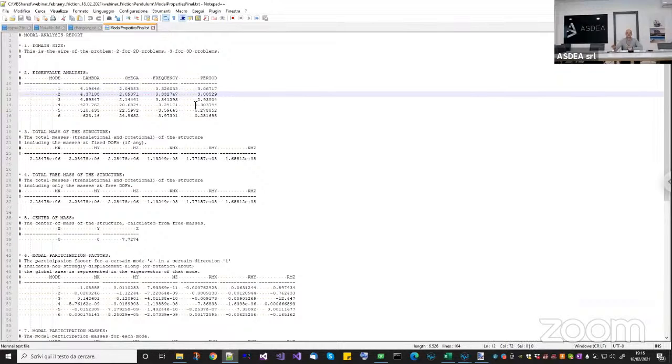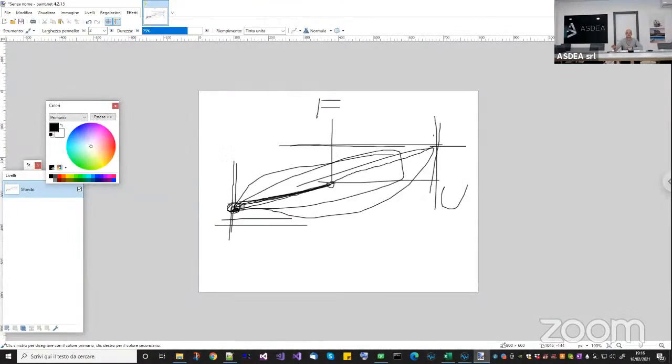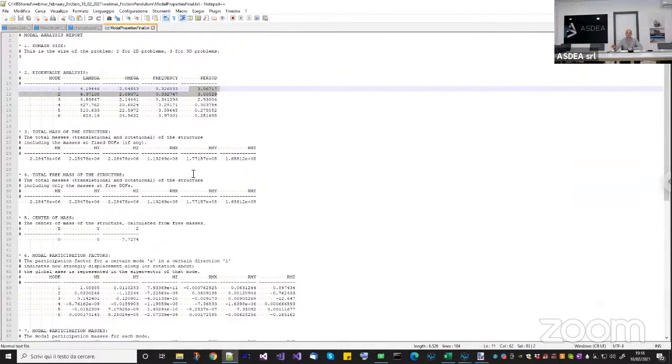In my opinion, I always do an eigenvalue analysis on a linear system. And if I have a situation like this, instead of running the eigenvalue analysis onto the nonlinear model, you can just compute an equivalent linear model, like I've done in this example. So I just take the equivalent stiffness of my isolator here, and then like I did in this sketch here, you substitute your nonlinear model with an equivalent linear model that describes the nonlinear behavior at that point of the analysis, and you run the eigenvalue analysis.